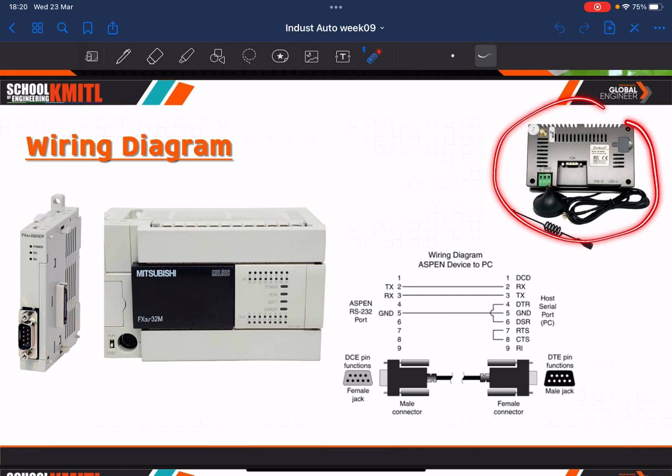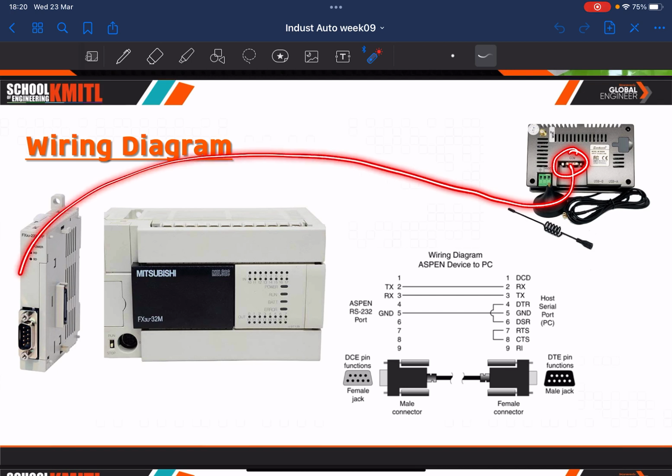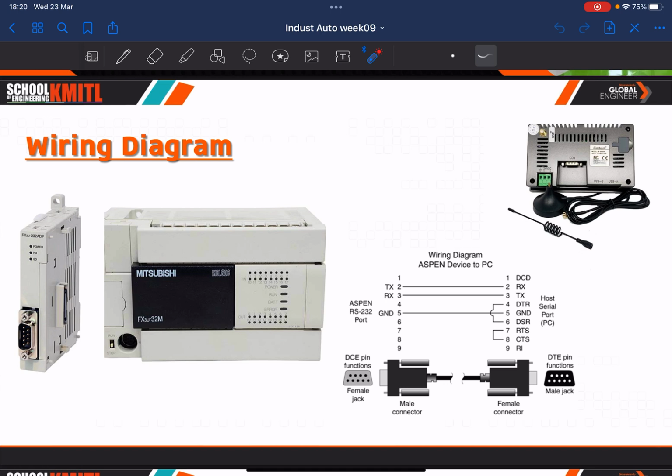You also have the HMI touch screen here, and you can connect them together using the RS232 physical style. Inside, you have TX connected to RX, RX connected to TX, and ground to ground.